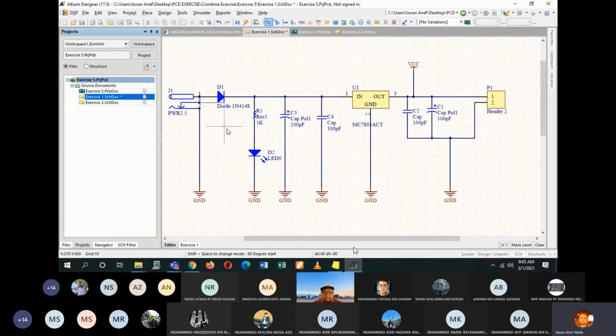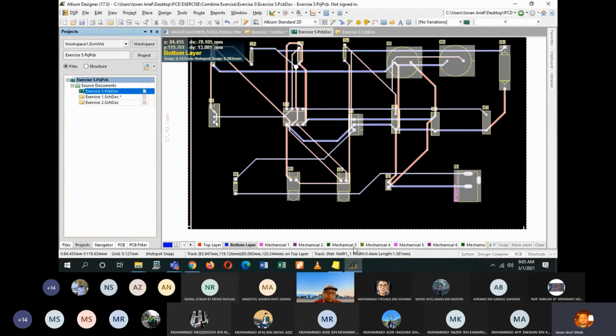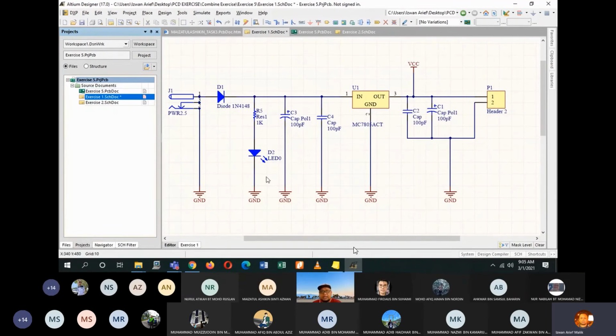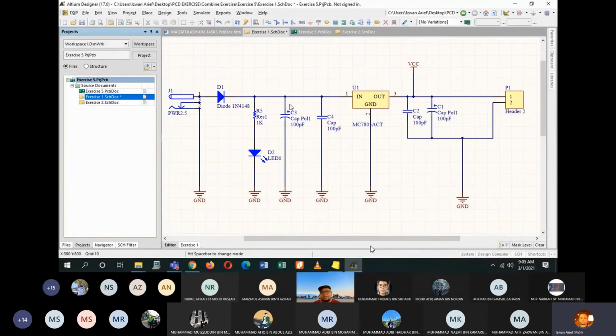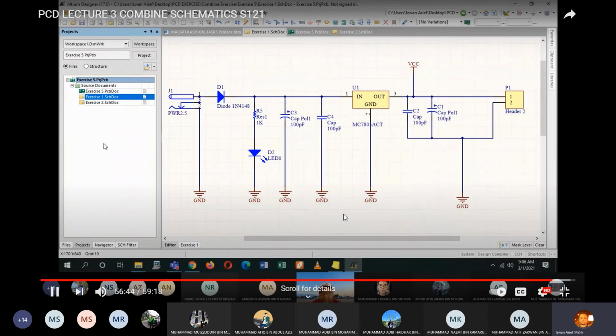From point 3 here there needs to be a connection to here, for example. So with any changes like this, you have to directly delete this PCB and redo them again. Because now the connection is not the same as the change you just made. But changes like moving this ground around don't matter. Any new changes, new component designators, or new connections, you have to redo. Then just make sure you save all your work, that's it.